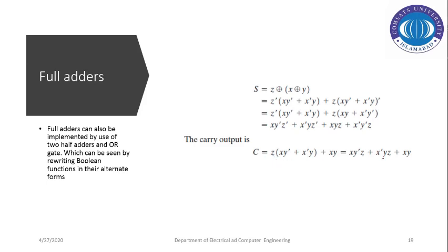Similarly, this is the expression for the carry output, and that can have the equivalent form, z and x exclusive OR y. X exclusive OR y is already generated in the sum output.